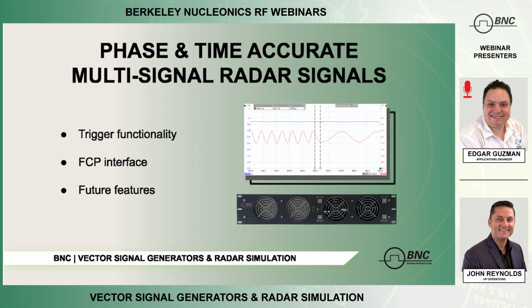So when you have a multi-channel system, a lot of time you're gonna want the channels to be phase coherent. You're gonna want them to trigger within the same time frame. So if you have one signal triggering, you need to know when the second one is going to trigger, and that needs to be accurate. And especially if you're doing communications that require two signals to be able to determine location, or you're sending pulses for communication.